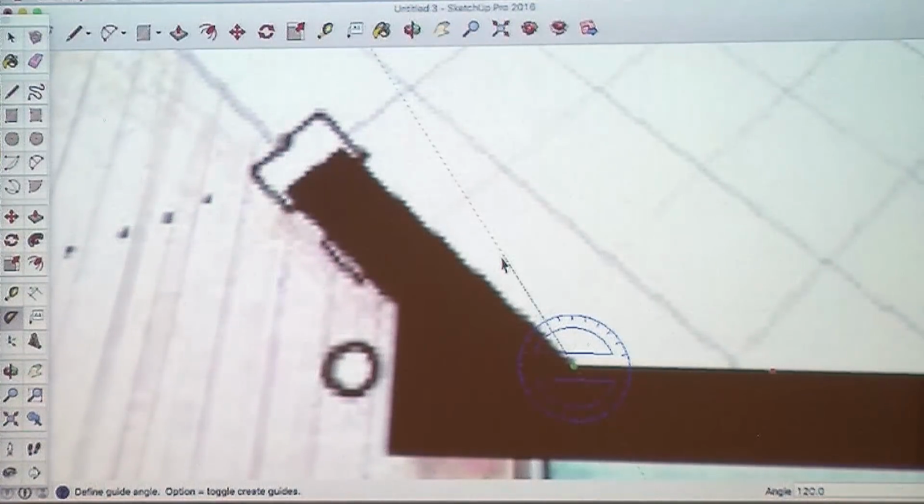And so here's a little protractor tip. I know it's hard to see, but in the bottom right-hand corner, we're seeing the angle that I'm currently protracting at. And as I move my mouse, it goes 97, 98.9, and so on. So if I hold it over here, I got it to stop at 135, but sometimes it's a little hard to figure out. Is it 135? Is it 136? Especially if your photocopy of your drawing isn't that great, it could be hard to figure out. The closer you get to the center of the protractor, you'll get snaps.